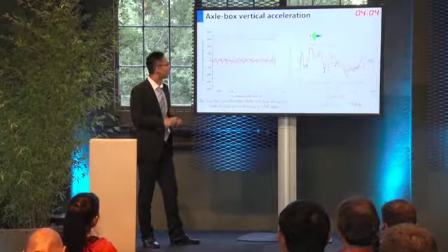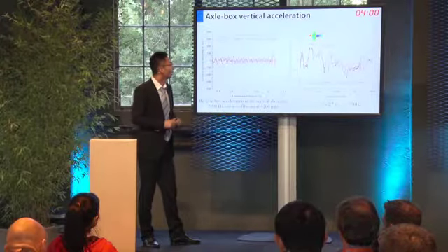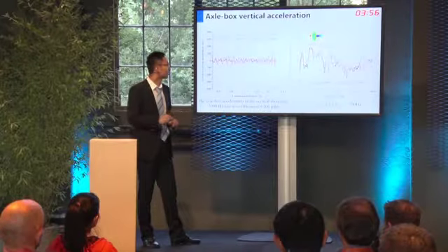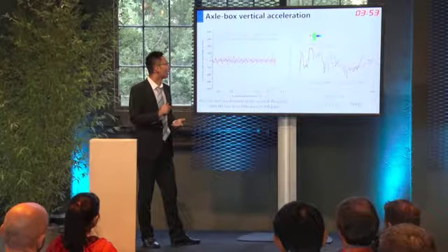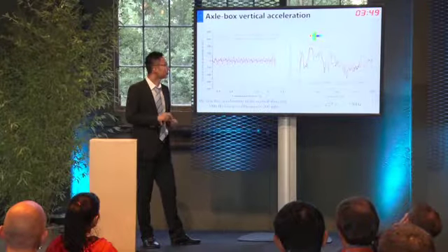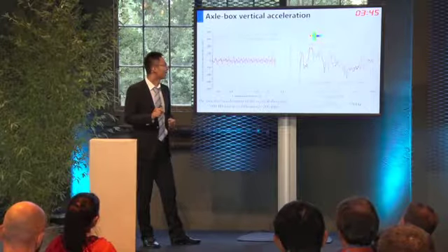We can also see that the maximum acceleration of the resilient wheel is at about 556 Hertz. This frequency is the second order harmonic wheel-rail force excited by the corrugation.